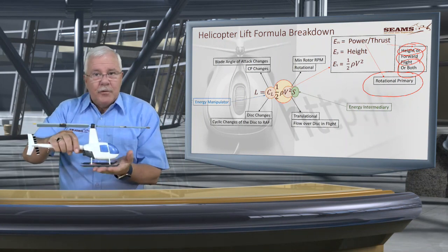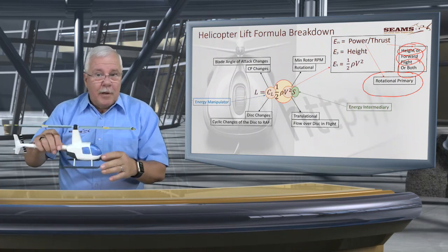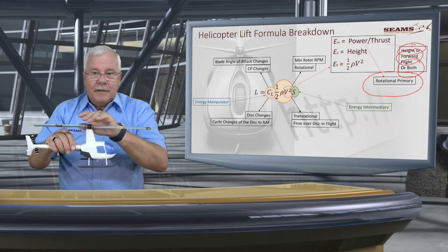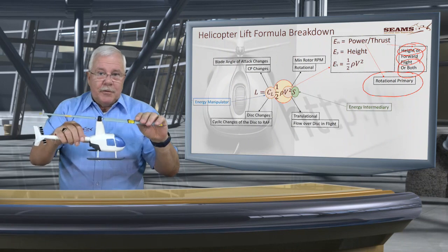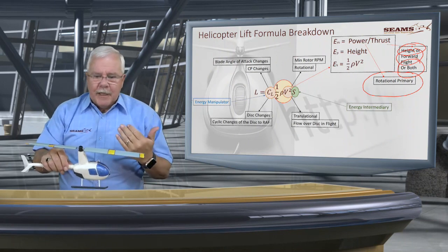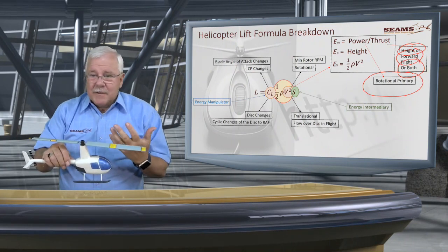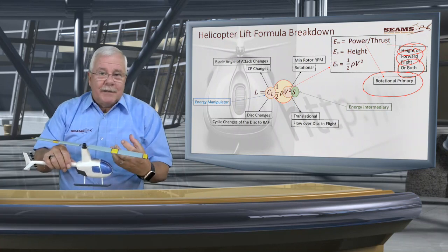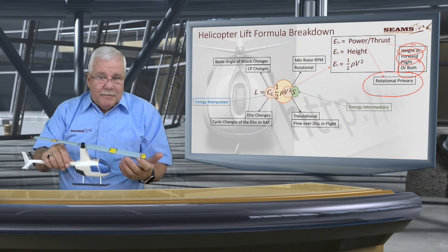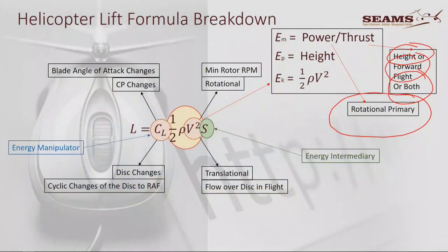No, you can do a skid off, or you can do a roll-off landing. There's helicopters with wheels, so that's not a problem. So they can roll on the ground until they have sighted the disc, and they make use of translational lift to get airborne if you're slightly heavier. Bigger helicopters, hover takeoffs, you don't necessarily do it unless the area is not suitable. Otherwise, it's a good thing to do a roll-off, if you wish. Okay. Up to you. How are you going to use it? So that's the primary function.